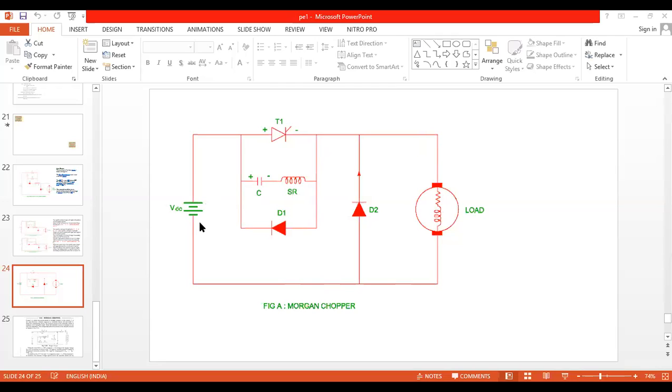Now case 2, or you can keep case 0 as the charging of this one. What is case 2? What do I have to do? I have to control the speed of the motor. Which component do I have to turn on? Case 2 is SCR T1 turned on with the help of the UJT firing pulse, and the energizing components are already completely filled with energy.